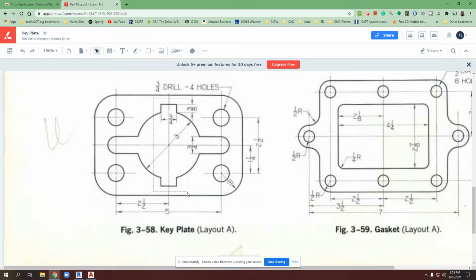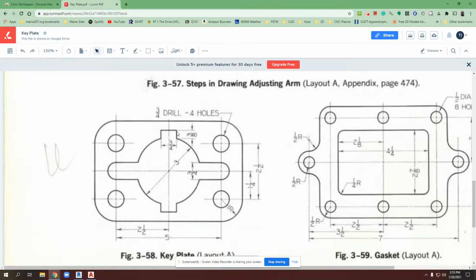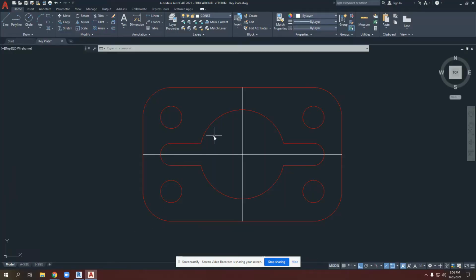Last but not least, we have these two notches, and these notches look to be 3/4 of an inch wide, and 3/8 of an inch deep, and specifically 3/8 of an inch from where these outside lines intersect with the circle. Well, we've already done a 3/4 inch notch over here. We know half of 3/4 is 3/8, and it looks like this little notch here is symmetrical from this mid line or center line here. So maybe, since I already have that white line left, maybe I can use that same technique that I used down here again, and that's what I'm going to do.